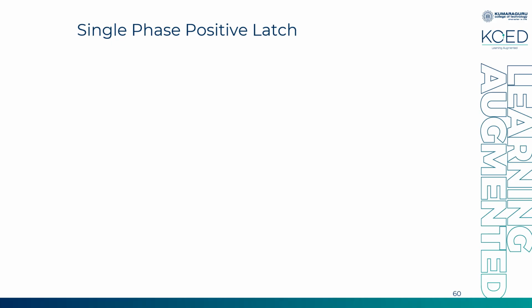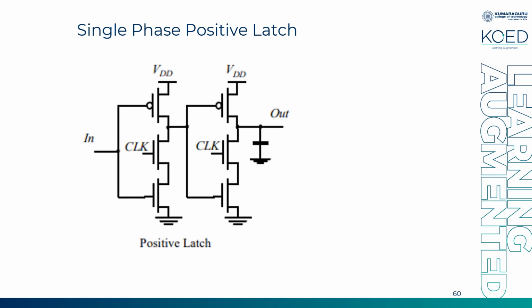So first we learn how to design a single phase positive latch. This concept TSPC we are learning as a dynamic logic style to design dynamic circuits. The very basic dynamic circuit we will start now: latch. First we'll design a positive latch using single phase clocking. This is a positive latch, where single phase clock only, clock, is used.